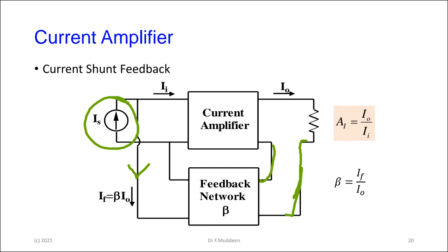The gist of it is to remember what is the type of amplifier. If I have to put feedback on that, if I give you a transconductance amplifier, the input is voltage, the output is current. So I have to sense output current, but I have to send back voltage. If I'm sending back voltage, the voltage has to go back in series. So that will be a series feedback, voltage series. Yeah? And so you go on.